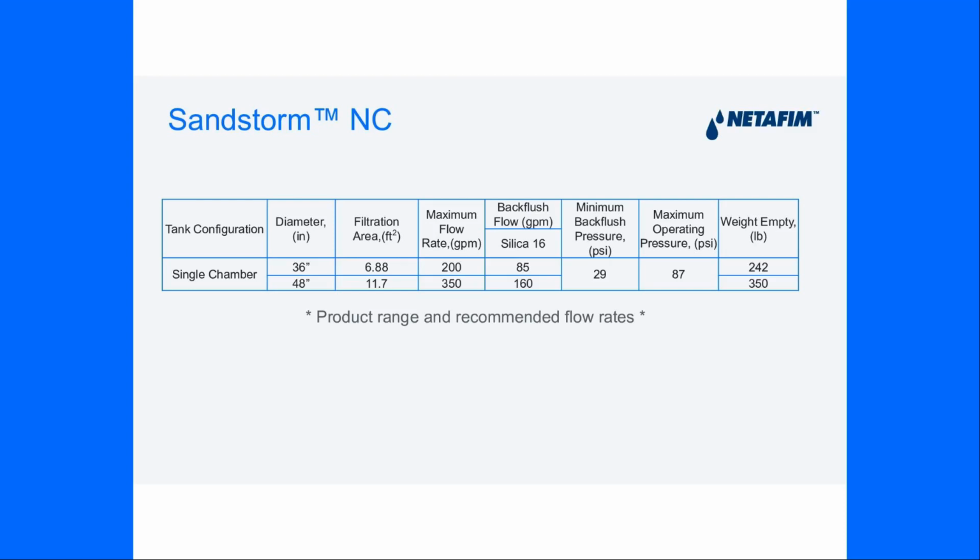And there's really only one other player in the market, with technology that's about 20 years old or so. The old AGF that we used to sell, I believe that tank is only rated at 80 PSI. And then it'll show you here the maximum flow rate per tank. But there should be an asterisk here. This really needs to be sized based off of water quality.